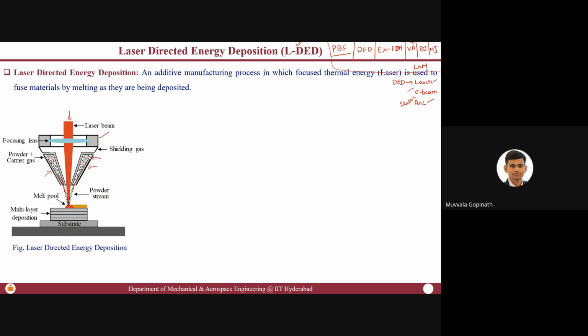They don't really melt at that point. Rather, the laser beam is partially absorbed by the powder particles, and the remaining energy reaches the substrate. It melts your substrate, and these powder particles drop into that molten pool. Once these heated powder particles get into the molten pool, they melt there and then.